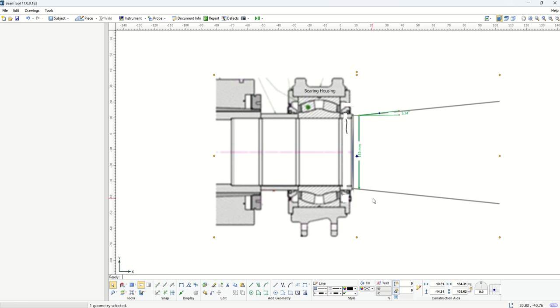And here the important factor would be that this depth or this dimension is 135, and the shaft body here is angled by around 5.74 millimeter. So to be able to deal with this geometry, we can click on the image and come to tools. And first, let's say move drawing to the origin. This tool helps us to choose which part of this image we want to set exactly at 0, 0. And my choice would be the corner here, which would be the location that the wedge can be closest to.